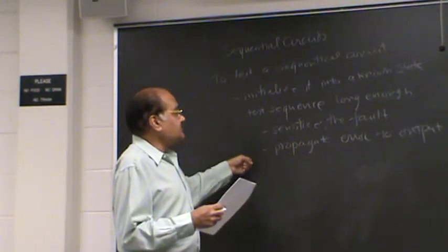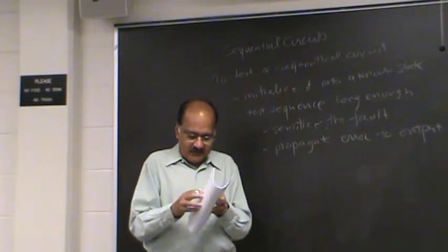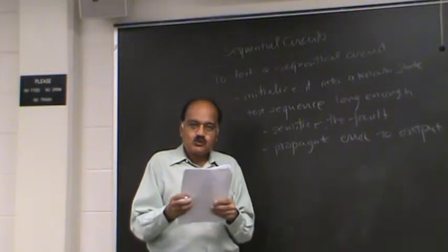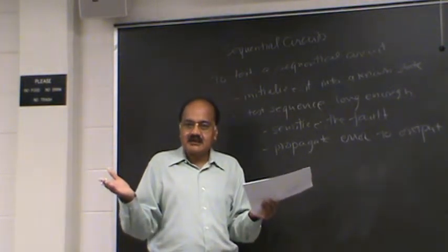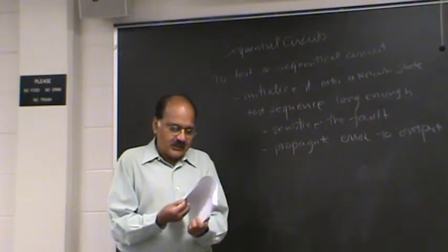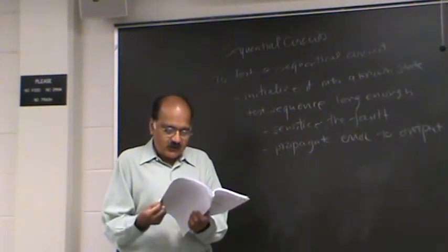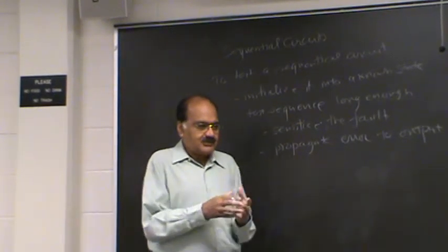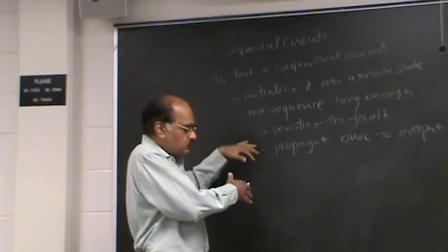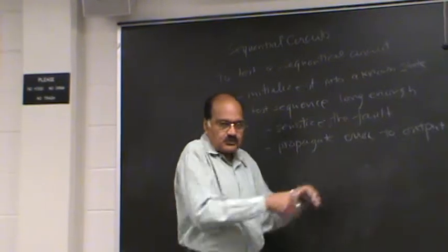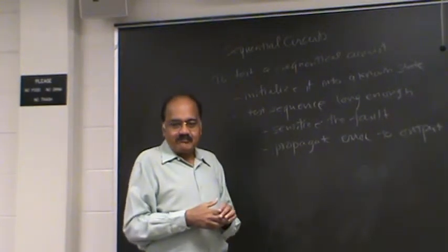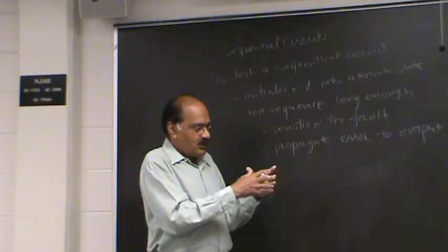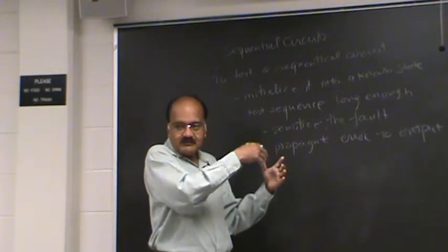In general, testing a sequential circuit is a difficult problem. And the usual approach, it can be done. So we have seen the D algorithm, and there is a version of the D algorithm that you can apply to sequential circuits. The only thing is that so far we have seen the D algorithm where you just start with the inputs and go towards the outputs. Now, if it is a sequential circuit, you need to somehow, at the site of the fault, get a D or D bar, and it may take a few clock cycles.